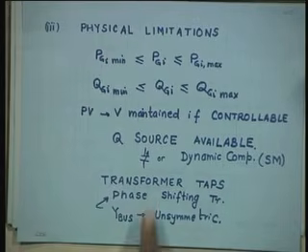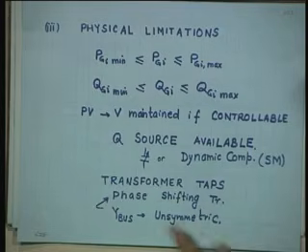There is a phase shifting transformer also, which controls the real power angle. So, the Y bus becomes unsymmetric if you have a phase shifting transformer in your system. The Y bus does not become unsymmetric if you have only magnitude controlling transformer taps.